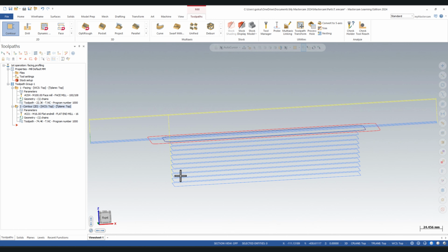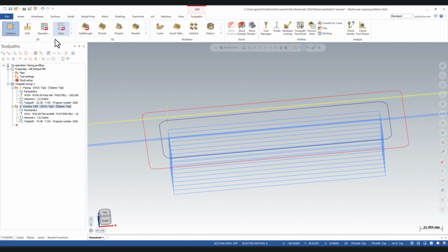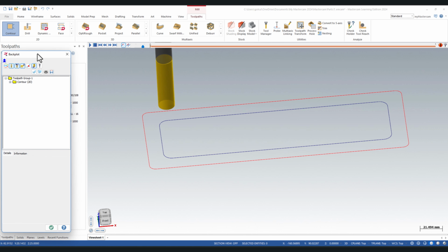The toolpath has been generated, and you can also backplot it because you are using 2D, so you want to do backplot alone. If you are doing it with a full 3D solid model, you will have verify options also. So we will see that verify option in the next video.